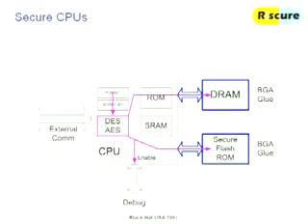Just a short break back to secure CPUs. So what we're seeing is that instead of a CPU being dependent on external storage and crypto and software, CPUs are changing in that they are actually storing secret keys inside themselves. They are blown in there by fuses or programmed into OTP, and they have their own crypto engines to operate on them.